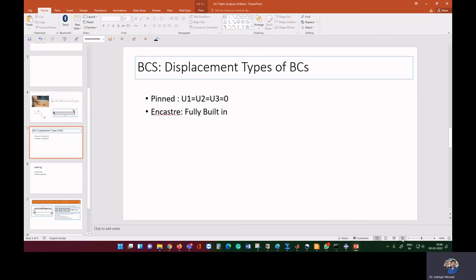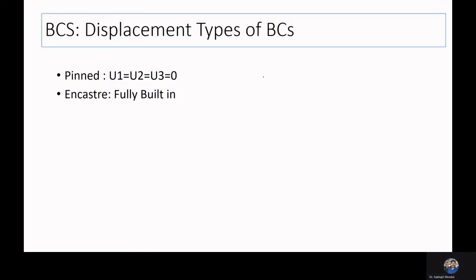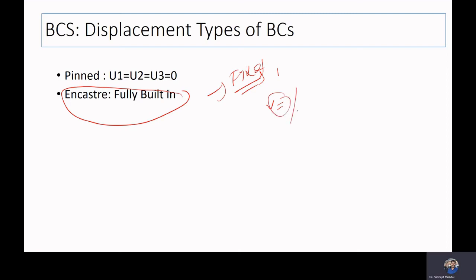So we have discussed 2 points. One is that we can choose the Encastre option to define a fixed condition. And another is that you can choose a particular degree of freedom and constrain it. We apply the constraint by making the displacement and rotation 0 on a particular degree of freedom.